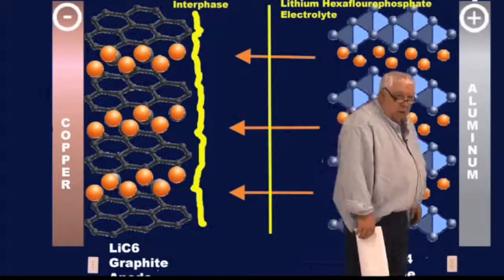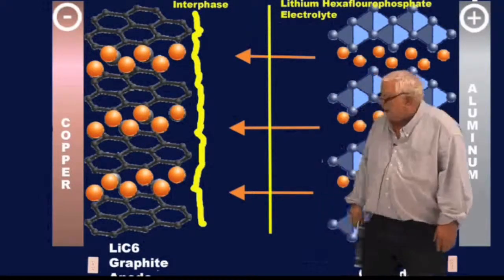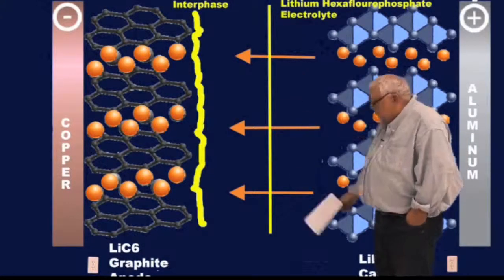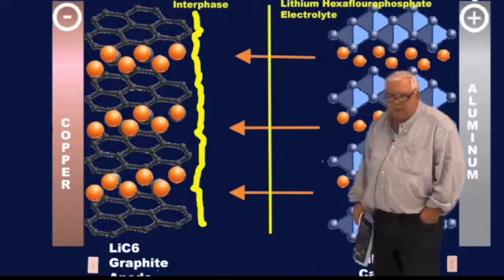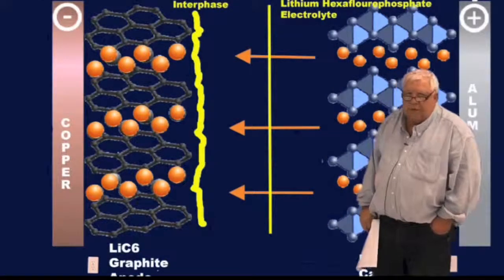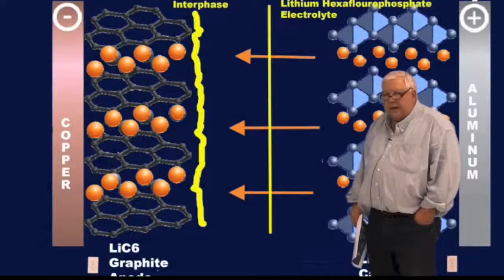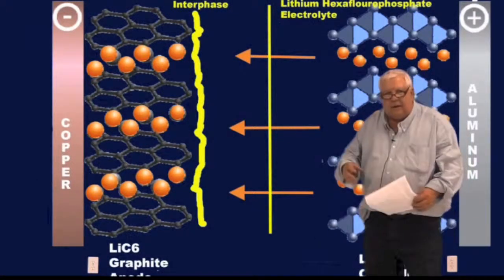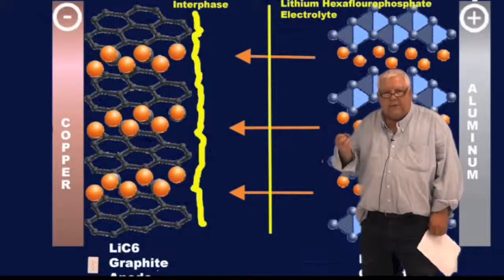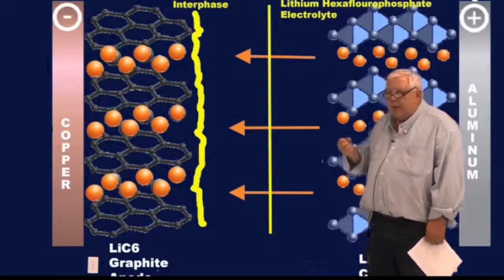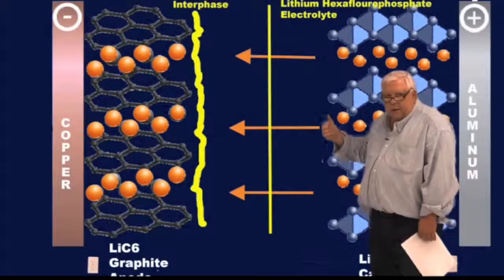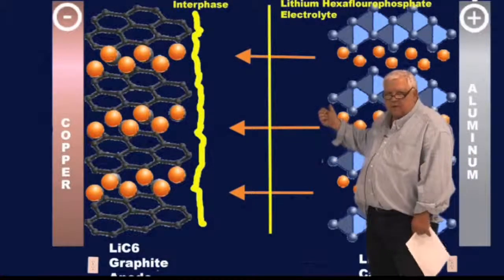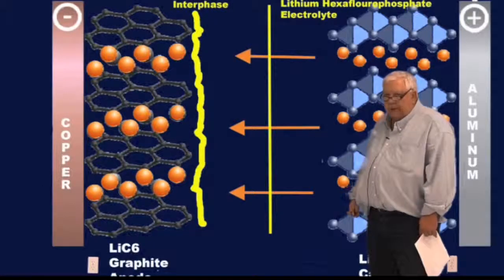Here's the problem. We have to have an electrolyte to get there from here. In the middle of the battery, we have a separator made out of polyethylene or polypropylene with holes in it. Where we say we have electrolyte on both sides of it, it's actually a little bit absorbent and absorbs the electrolyte. And so we have a wet napkin made out of plastic trash bag that has absorbed a mixture.